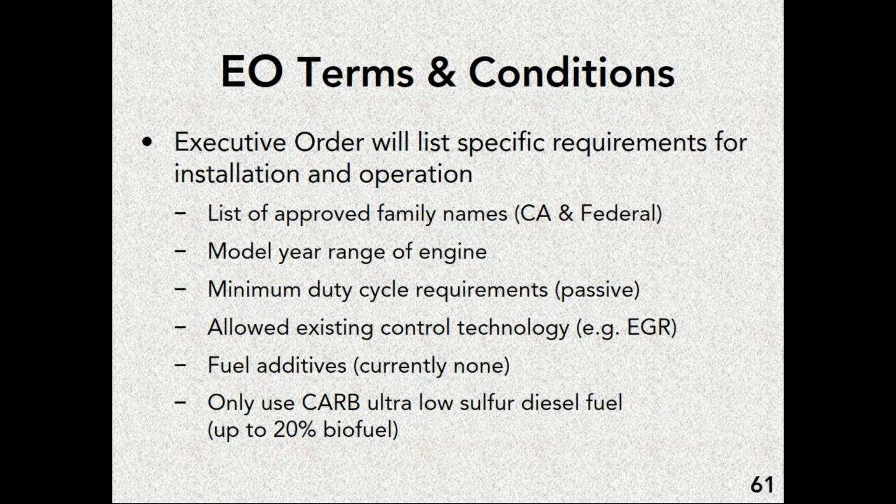Many filters, it says currently none here, but since I put this together, there are several filters now that will not offer you a warranty if you put fuel additives in your system. And a lot of systems will not allow you to install a filter or maintain a warranty on a filter if you use biodiesel or very ultra low or a diesel that has too much sulfur.